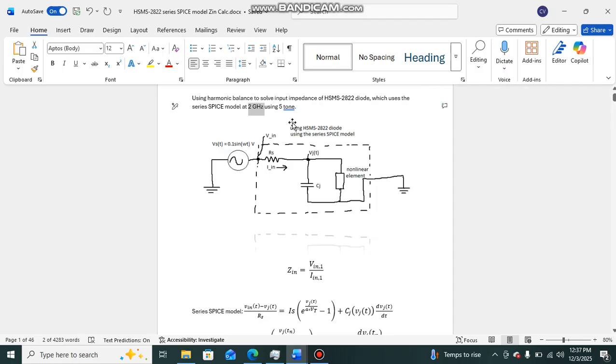So what you would want to do is down convert that frequency to, for example, 100 megahertz, and having that as the modulated signal, extracting the message signal from that modulated signal will be a lot easier. So that is the number one reason for creating a mixer in your circuit design.